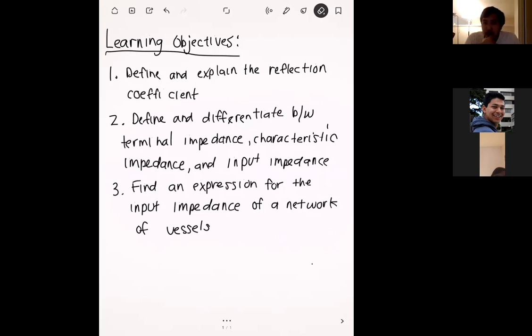Meshing is a complicated question, and what complicates things more is that there are different ways to measure mesh quality. What can happen with hexes is that because they can be distorted more than tets, people go a little bit crazy with that, and they do some really crazy stuff with hexes.